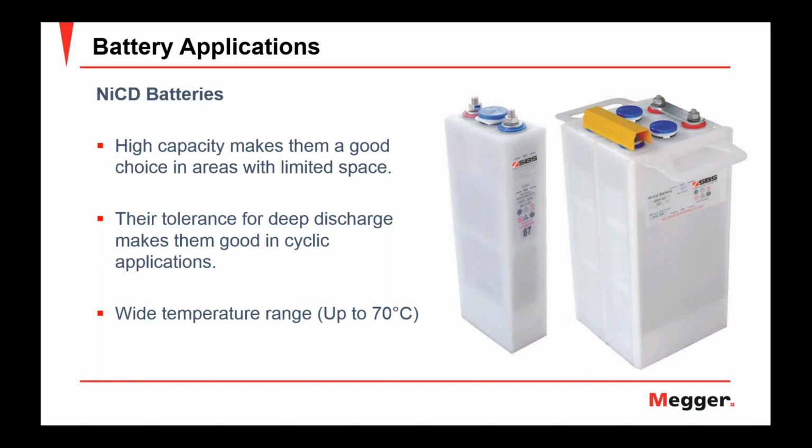They're also very good at wide temperature ranges. They can be used up to 70 C. That doesn't mean temperature doesn't affect them. It does. It's just they're more tolerant of it. This is one of the reasons that in a lot of handheld tools, you'll see NiCad batteries used, because these can sit on the shelf for a long period of time. I know my portable drill, I'll leave that on the shelf for months on end, not touch it. And when I pull it out, my batteries will be real low. If I was to use a lead acid or a lithium ion on there, and I left it where it got down to near zero, they would no longer work. A NiCad battery can actually do that.